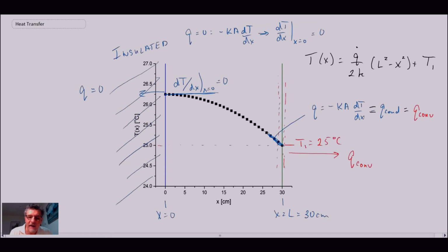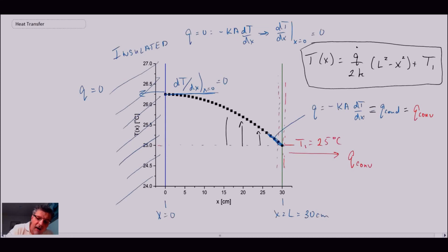Anyway, that gives us an example of applying energy generation. We derived this equation, having the internal heat source, and once we had that, knowing our boundary conditions, we were able to come up with the temperature distribution inside a wall. Essentially, the energy generation inside the wall causes the temperature to go up within the wall. That's the net impact of the thermal generation taking place inside a concrete wall while curing is going on. So that gives us an example of energy